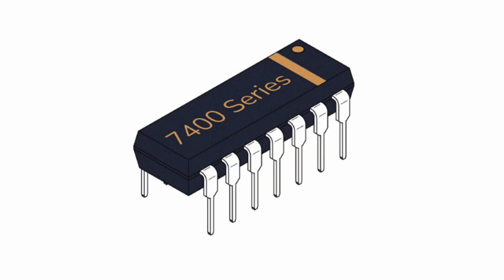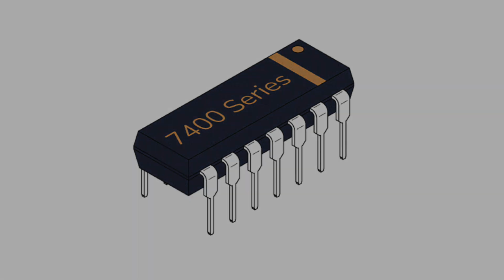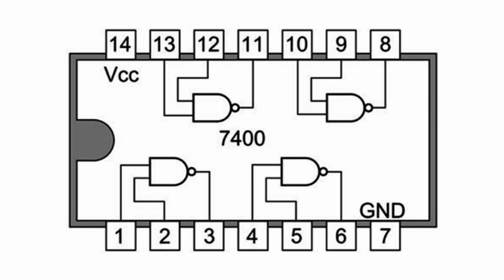Where the transistors are literally microscopic. Because we can't see the parts on the chips, chip makers label the chips with identifying numbers. The chips we will use in this video are 7400 chips. The 7400 chips contain 4 NAND gates, as shown here.